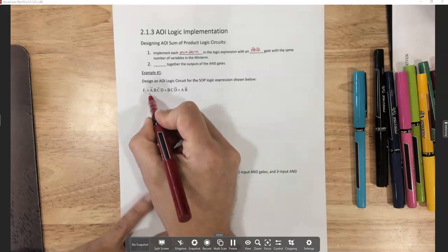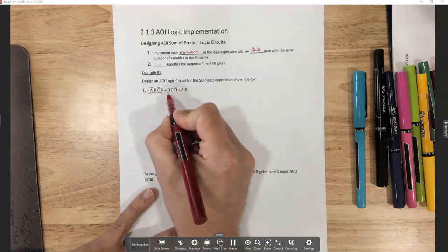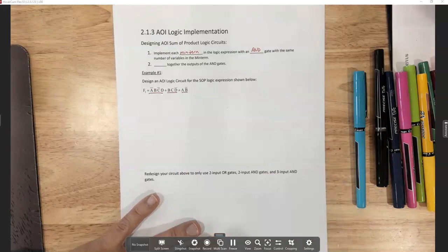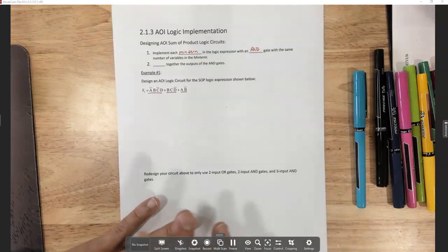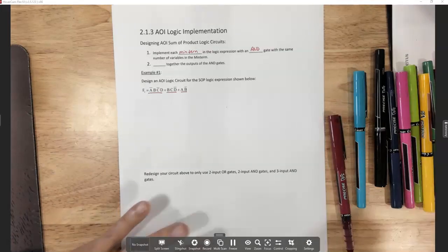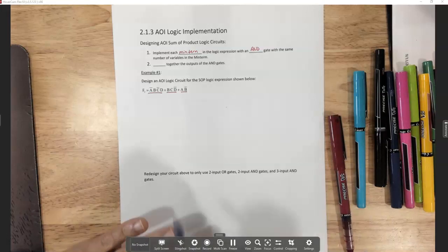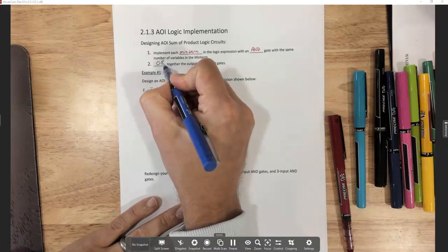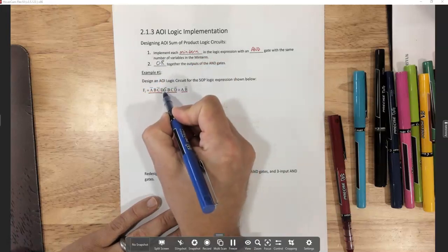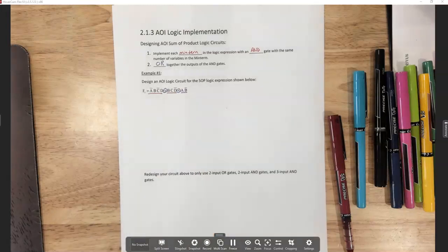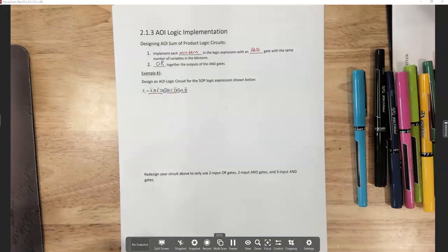In this first example, there are 3 minterms, and it's going to take AND gates to create those minterms, those combinations. Then to get them to come together to make the full expression, we're going to use OR gates, because those sums, those pluses, really mean OR.